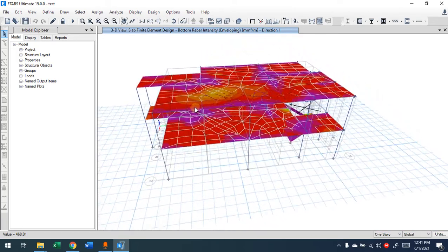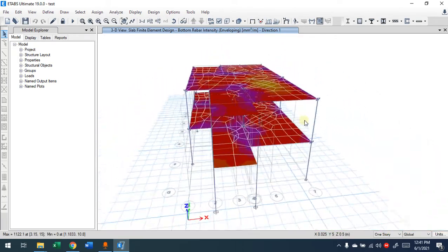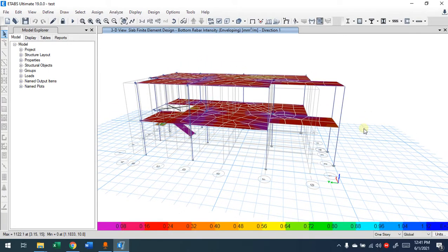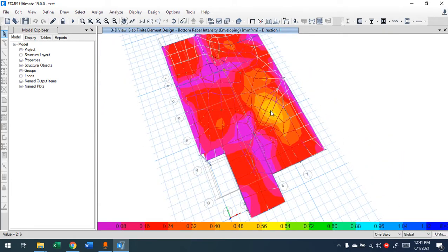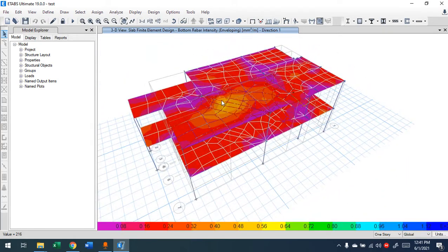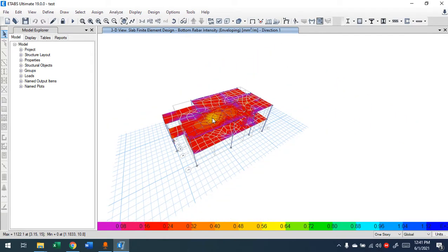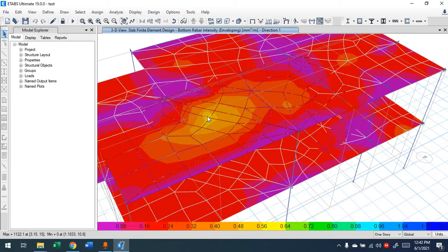So in this way, but this is finite element method, remember. If you can divide this into a column strip, you can see much more conventional way of designing that you've seen from the textbooks from outside. But this is how we would use this design outside. We'll basically take the value that we have here. So if I take the value, then I can use this value to exactly say that this much amount of reinforcement is per meter square. Then I can find the area rebars by myself. I can find the area, whatever I want by myself in that case.